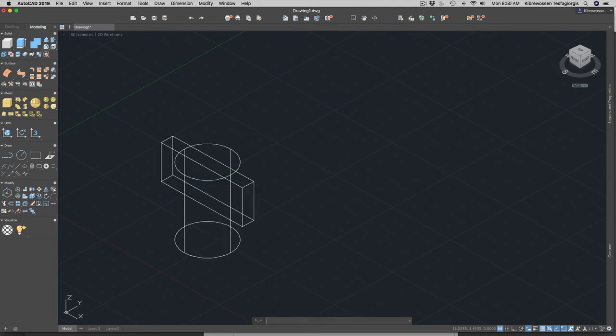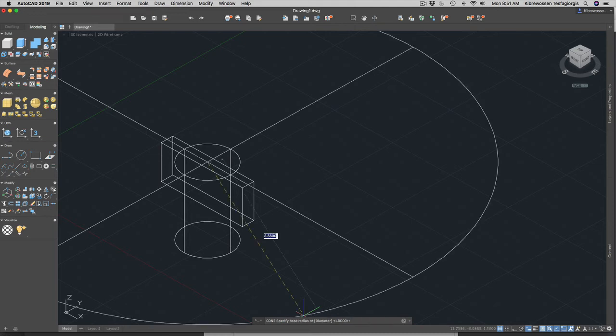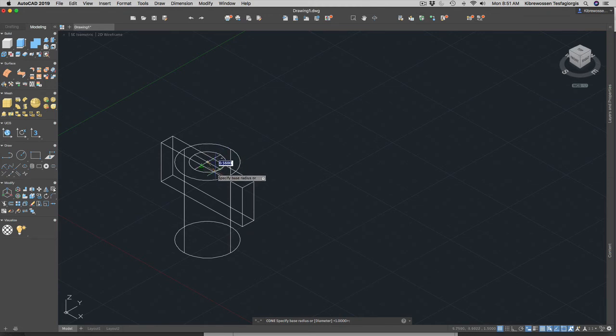Okay, then now the next one is you need to do a cone. Then there's a function called cone. Then the cone center is going to be the same as the cylinder, so it will be 5.75, right? Was it like that? Then 3.75 and 1.5. Yeah, right at the center of the cylinder and the top of the box.